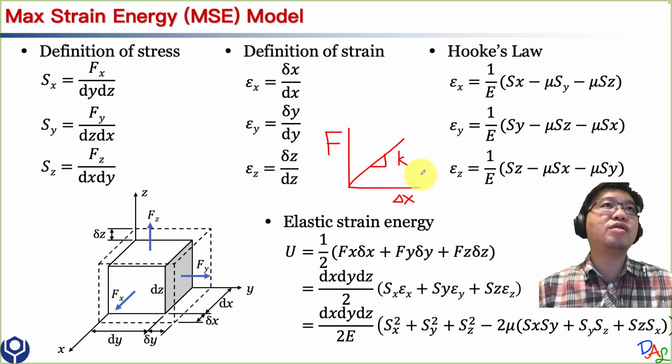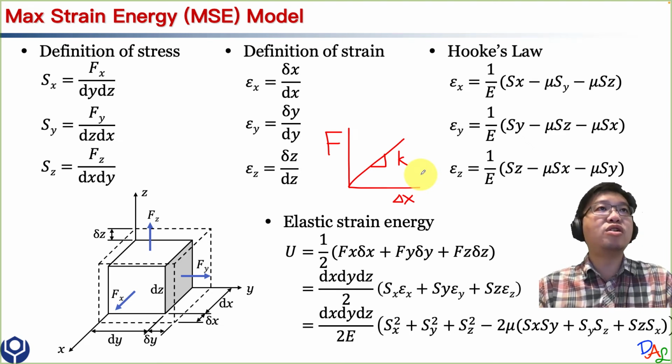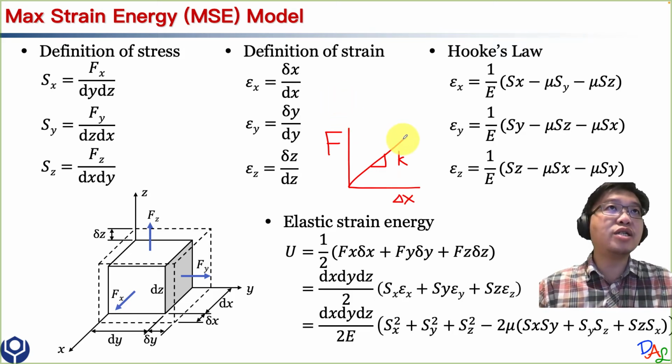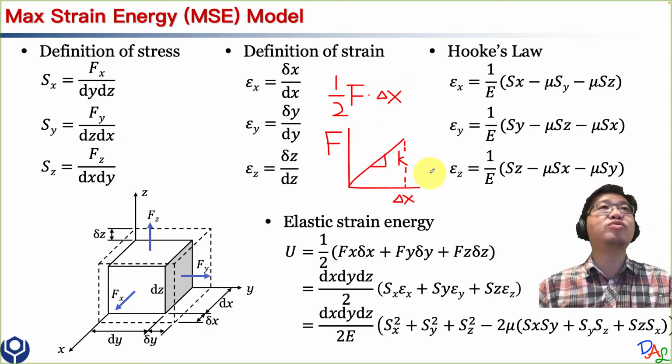The more force applied, the more deformation you will get, and they have a linear relationship. The work done basically is the integral of this part. When you calculate the integral, it's actually 1/2 of F times delta x. This is what I wanted to say.